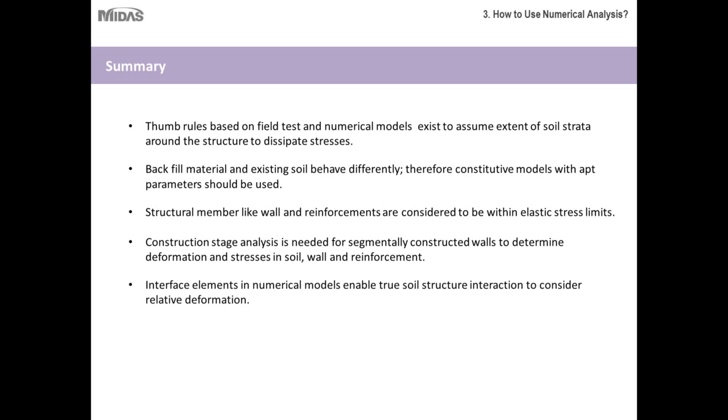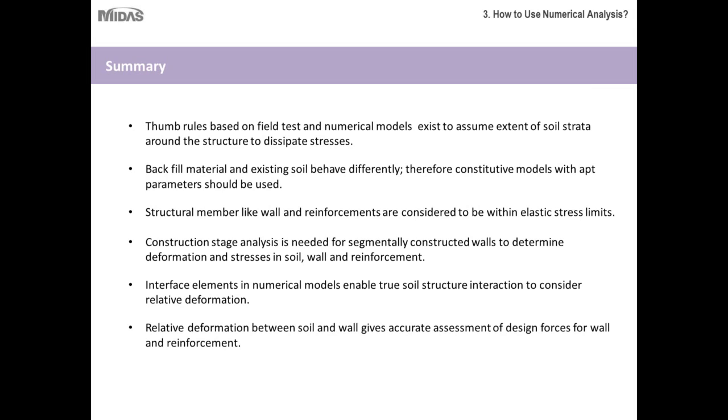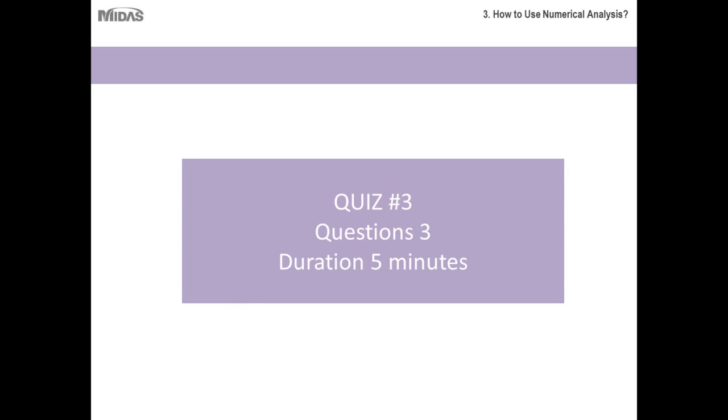The construction stage analysis is needed for segmentally constructed walls to determine the deformation and stresses in soil, wall, and reinforcement. And the interface elements in numerical models enable true soil structure interaction to consider relative deformation. And relative deformation between soil and wall gives an accurate assessment of design forces for wall and reinforcement. And finally, interface properties are dependent on soil type, and inputs can be obtained from the field test.